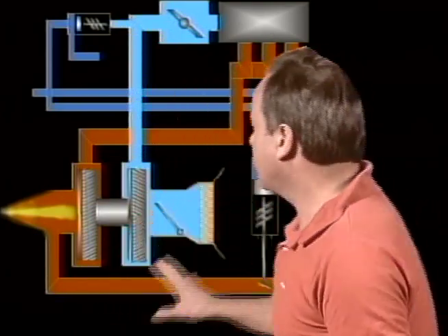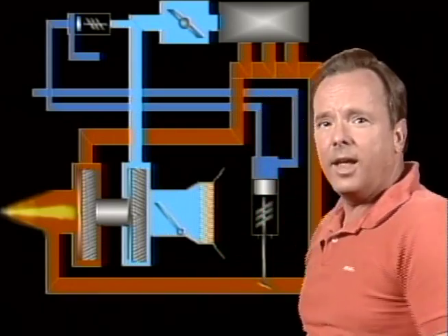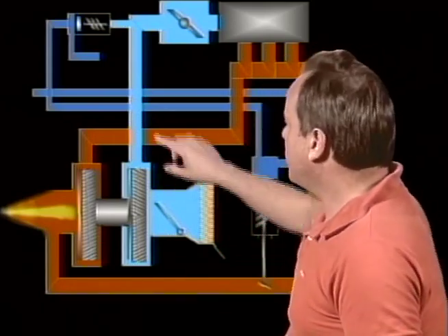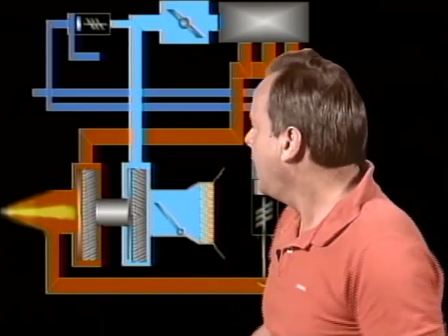All right, there is another thing in this system. We're talking about a turbo-normalized system, and that is called the pressure ratio controller. And it says, look, we don't ever want the ratio between deck pressure and ambient air, the outside air pressure, to be more than 2 to 1, because you'd be overheating the air, compressing it too much. This system is designed to only take so much. So the pressure ratio controller limits the ratio between upper deck pressure and ambient pressure.